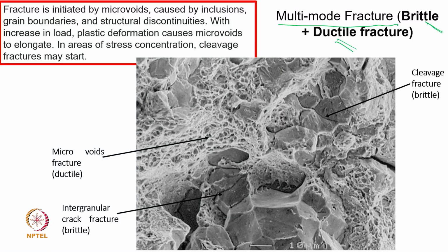Again, here we are showing a microvoid fracture, which was shown in a slightly different form on a different slide. Microvoids, you can see, are spread completely across the surface. Cleavage is basically on the boundaries of the grains, while intragranular cracking penetrates the grains themselves. So the fracture in this case may be initiated, not 100%, from microvoids, because there is a slight discontinuity.